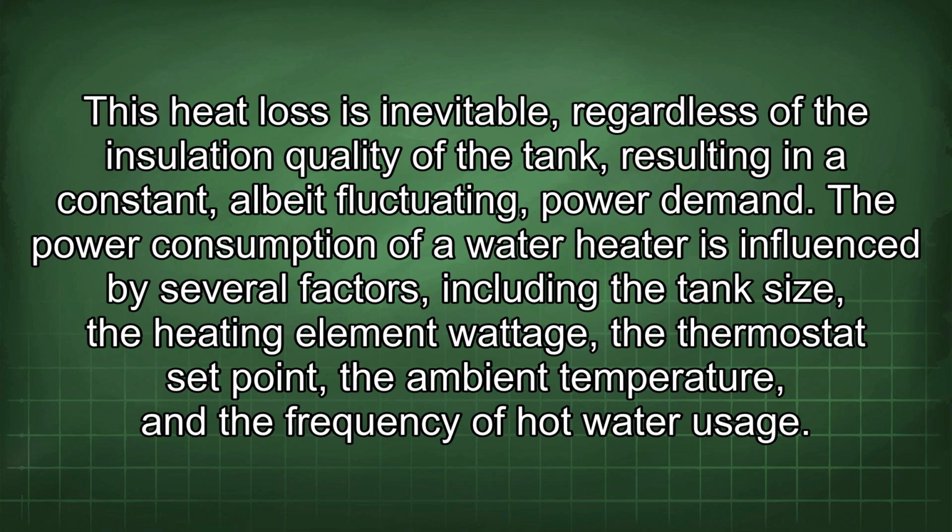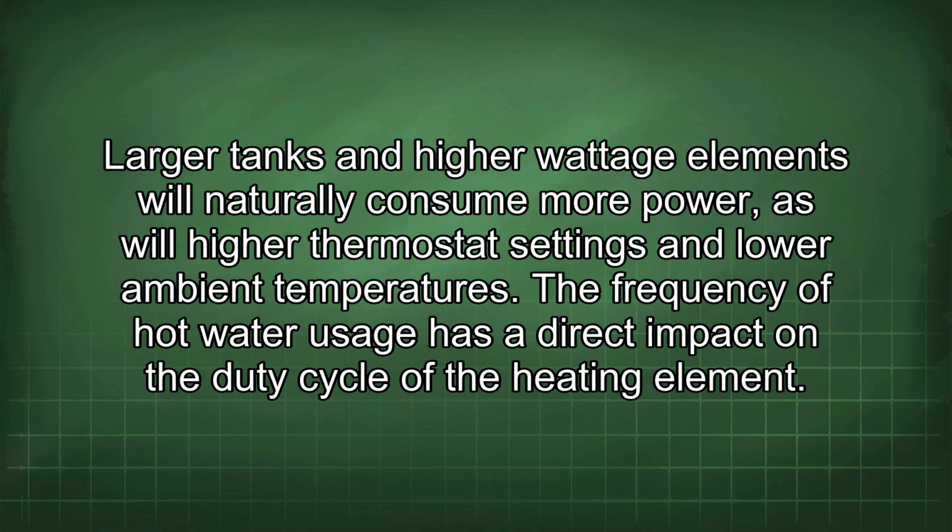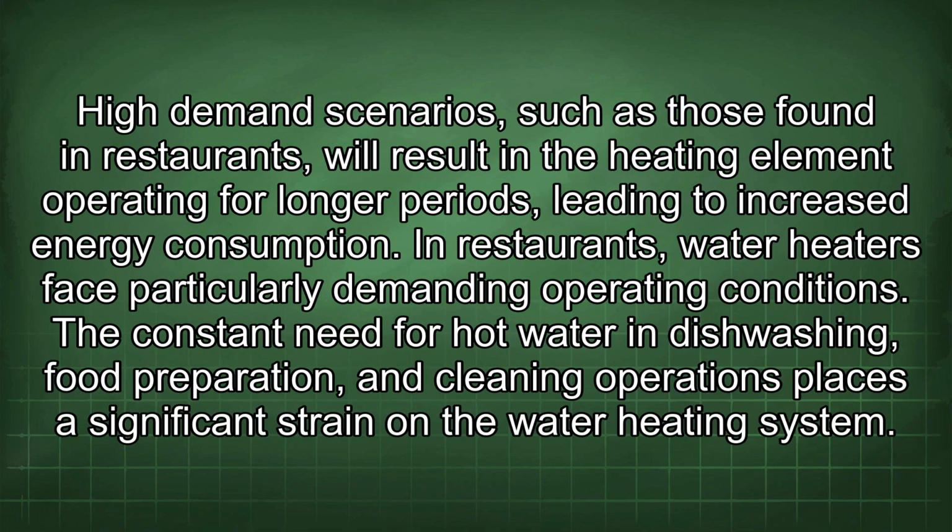demand. The power consumption of a water heater is influenced by several factors, including the tank size, the heating element wattage, the thermostat set point, the ambient temperature, and the frequency of hot water usage. Larger tanks and higher wattage elements will naturally consume more power, as will higher thermostat settings and lower ambient temperatures. The frequency of hot water usage has a direct impact on the duty cycle of the heating element. High demand scenarios, such as those found in restaurants, will result in the heating element operating for longer periods, leading